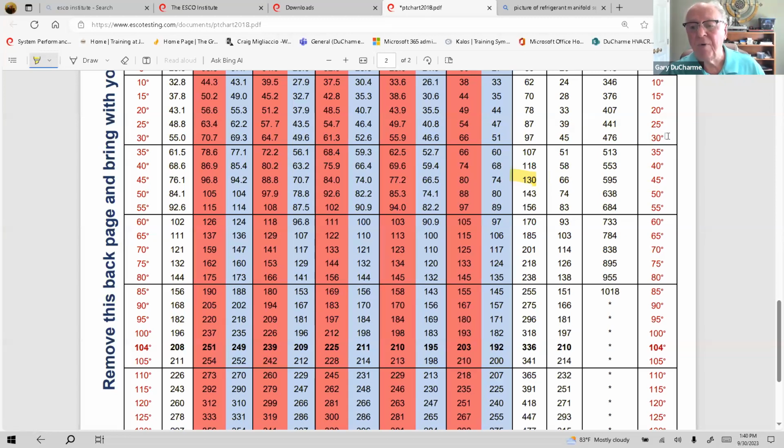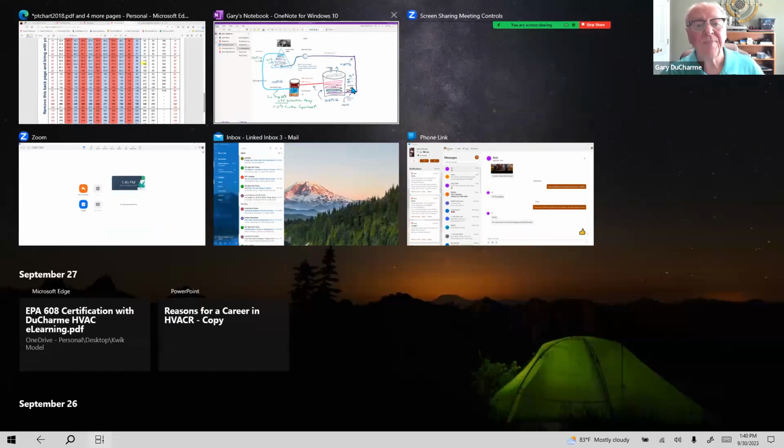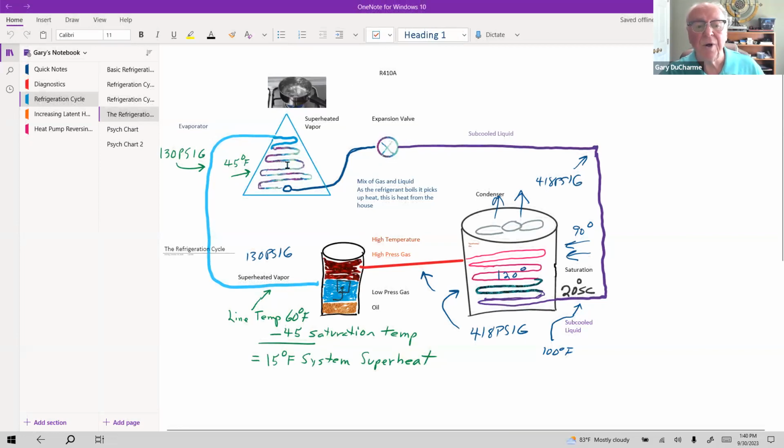So what happens at that point? The moisture in the air that's coming across that evaporator starts to freeze on this coil. Now, you've probably seen pictures or heard about coils that can just continue freezing and become a big ball of ice. And this is terrible for the compressor, because this means that liquid refrigerant is coming into the compressor, causing damage. As soon as any liquid goes into the compressor, it may not kill it immediately, but over time, it lessens the efficiency of this compressor, and it will take it out eventually.